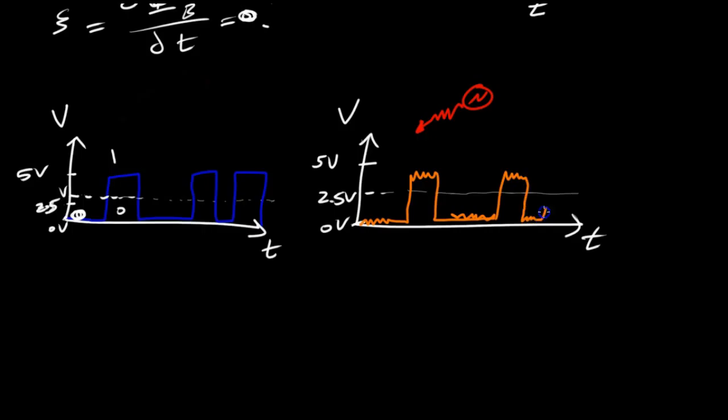Just electromagnetic interference. And you can see that even though I have had electromagnetic interference, I still have the defined threshold, and this is still read as a 1, as it was a 1 here and a 0 here. Anything below this line is a 0, anything above it is registered as a 1. So what I've done here is introduced a kind of immunity to this digital system, to not have to worry about electromagnetic radiation as much.